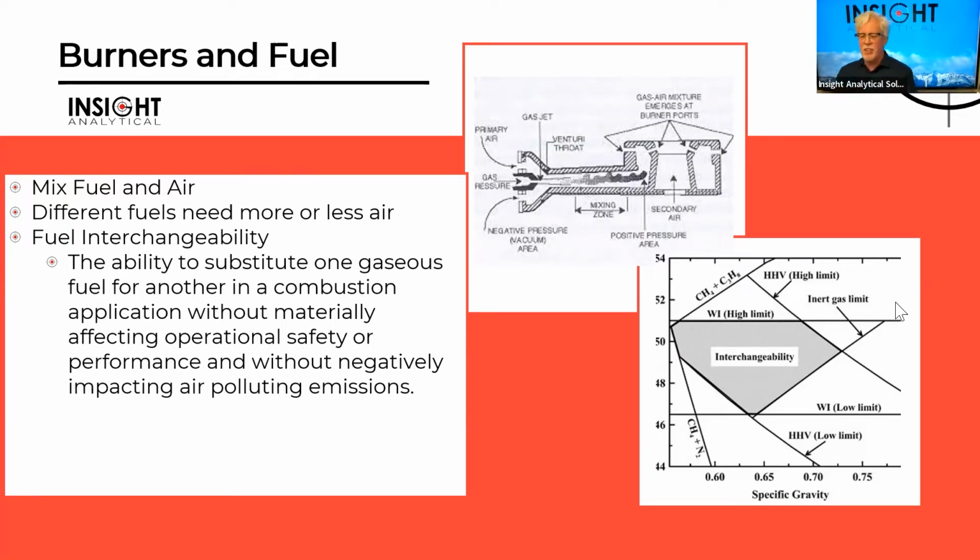Flame outs, damage to the turbines. Same with big reciprocating engines. So we've got to have an understanding of what's my fuel composition like. If you think about it, this is why we have specifications on gasoline quality and octane numbers, or diesel and cetane numbers. We want to know what the combustion properties of that fuel is, so that we can tune how we're going to mix our air to fuel ratios to get the best efficiencies out of our engines.